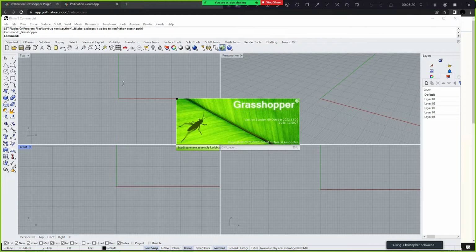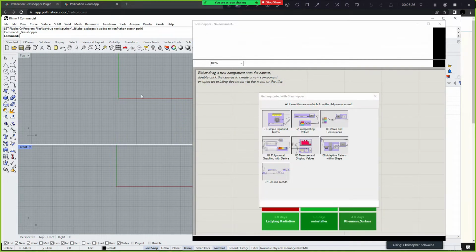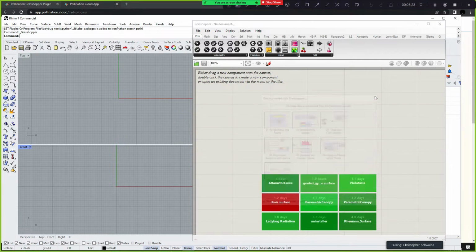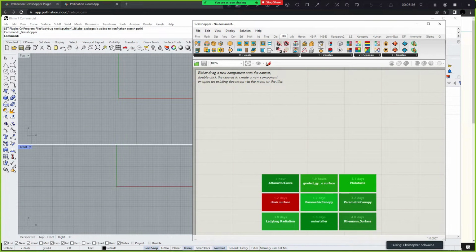And then the other place that you want to check is in your Special Folders in Grasshopper, just to make sure, because sometimes when you run an uninstall of Ladybug, it won't remove everything. So up here I have Ladybug and Honeybee, which are these two tools here, LB for Ladybug. I've run that installer, so I do have them.